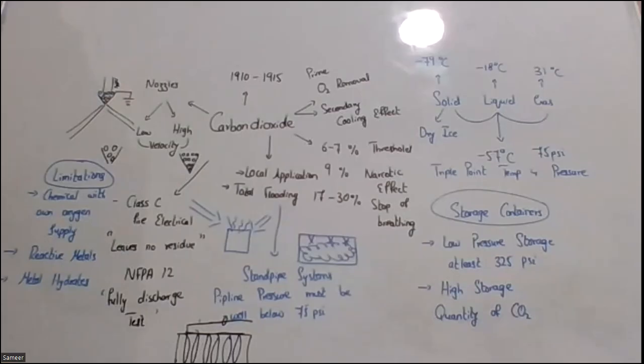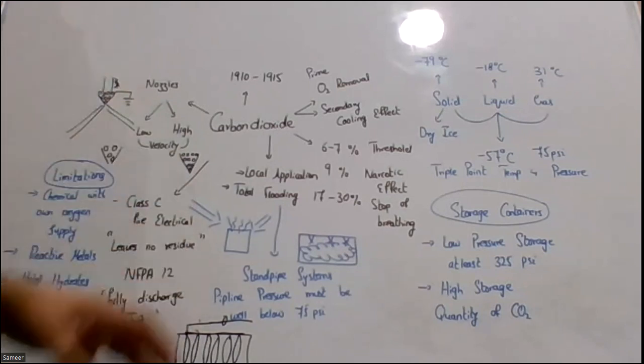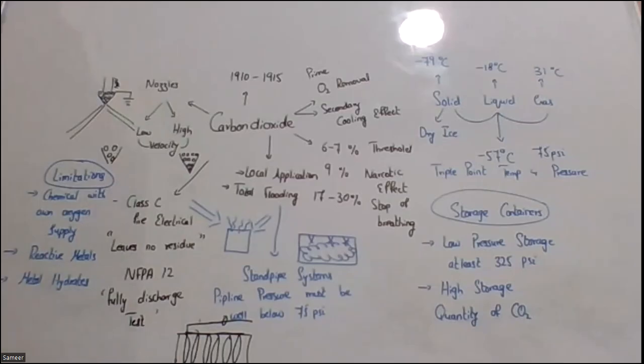That is why you seal off the whole room. Total flooding means the whole room is completely sealed off, and then the carbon dioxide is exhausted from the nozzle itself. The holding time of the gas means for how long the gas is going to remain in that room. That defines whether the gas is going to be very effective for the type of combustibles that are available.